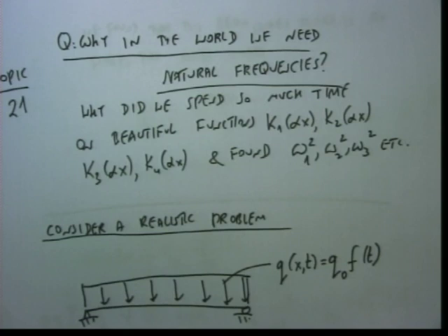These modes happen to be a very good tool for expansion. One could have said, okay, maybe I don't know the mode, so I'm not going to expand in terms of the mode. But for uniform beams, I already gave you modes. In today's homework, I did ask you to find some mode shape for a particular case. For non-uniform beams, the finite element method provides these mode shapes. So mode shapes of free vibrations are always available. Then we expand the solution in terms of these mode shapes.